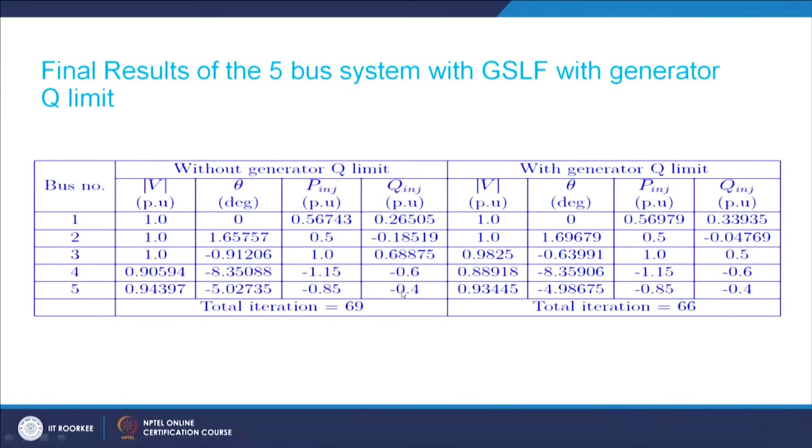But if we look at this Q injection by all the generation and the load, there is a very surprising thing. If you see my total amount of reactive power which is being absorbed, now here when I say minus, because these are injected values which are minus, then basically they are physically being absorbed. So, this amount of reactive power is physically being taken away from that bus.